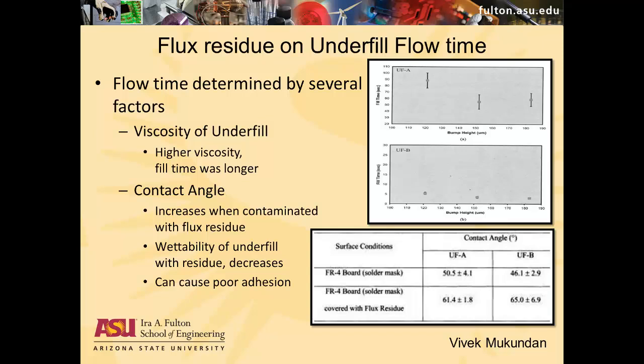As seen in the plot, the sample with a higher viscosity has a higher fill time as compared to the other sample. The other important factor is the contact angle. The contact angle increases when the sample is contaminated with the flux residue. This decreases the wettability of the underfill and hence causes poor adhesion between the underfill and the PCB. Now I'll let Manoj continue the presentation.